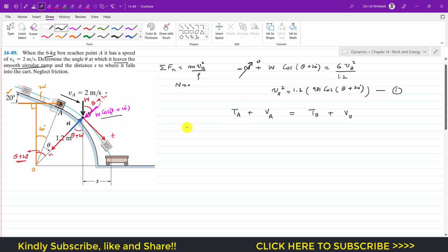The kinetic energy at point A is 1 divided by 2, mass is 6, times Va square, the velocity at A. The velocity at A is given, which is 2 meter per second. So this is 2 square, plus the potential energy at point A. For that, let's define our datum line at point B. This is our datum or reference line for the gravitational potential energy.